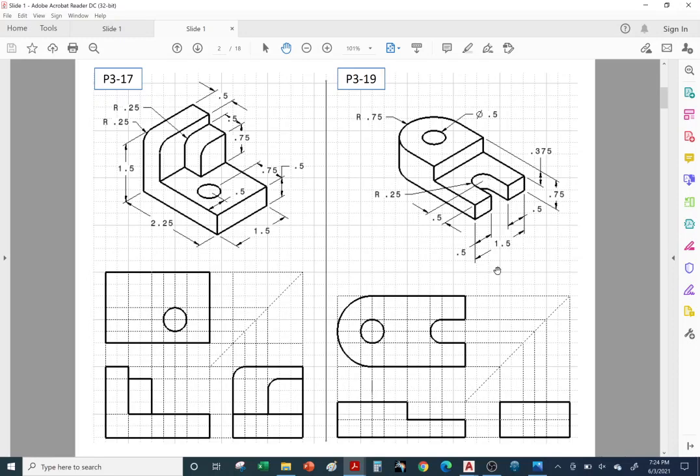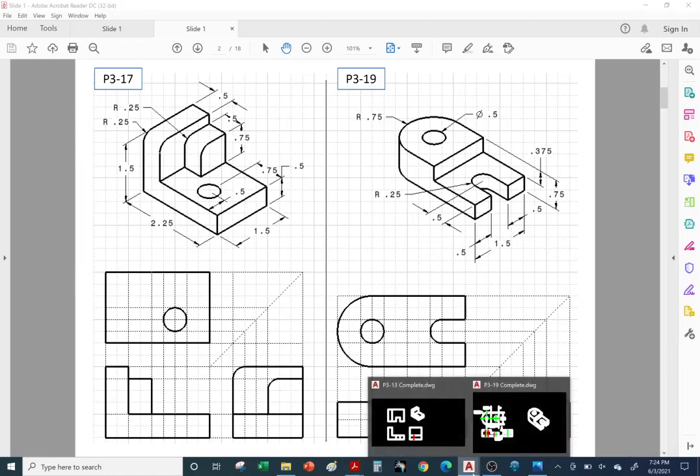Now, isometric views on a drawing, when we create a real drawing out in the real world of our front, top, and side view, the isometric view is considered reference only. It's just to help the machinist or inspector visualize the part. So since it's reference only, we don't dimension it like we have it here on the handout. We actually dimension the 3 views down here. And we do not include center lines nor hidden lines. There are some rare exceptions, but 99.9999% of the time, we do not dimension an isometric view. No hidden lines, no center lines. All right, so let's go back.